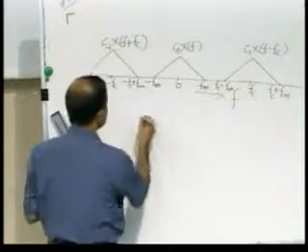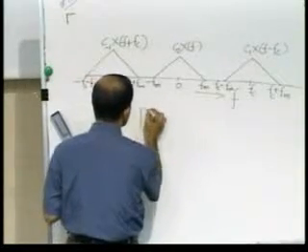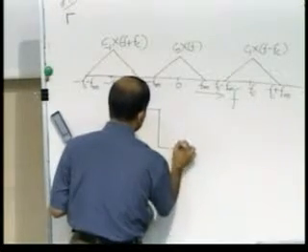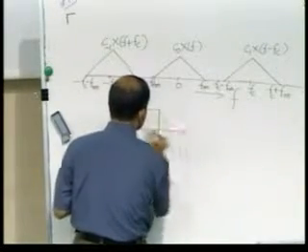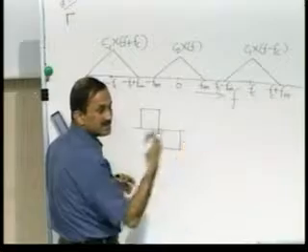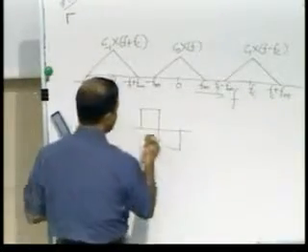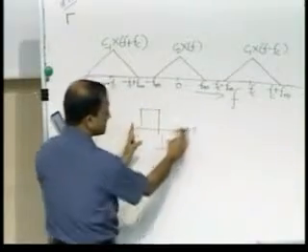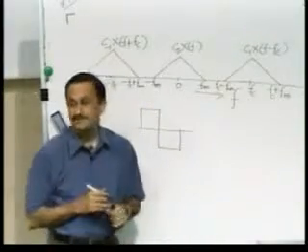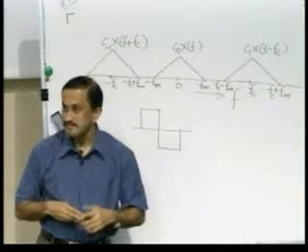What can be the simplest possible periodic pattern? Something that is constant for some time and again constant for the remaining time. And this can be constructed very easily with a circuit which either passes the waveform as it is or inverts the waveform. Right? So, this is called a gating pattern. Now, you could make this gating pattern periodic with a period that you desire, right?